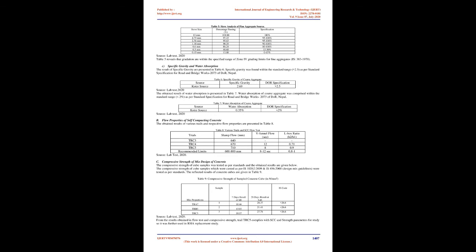Source, Lab Test, 2020. Table 5 reveals that gradation is within the specified range of Zone 4 grading limits for fine aggregates, IS 383-1970. C. Specific gravity and water absorption. The result of specific gravity is presented in Table 6.